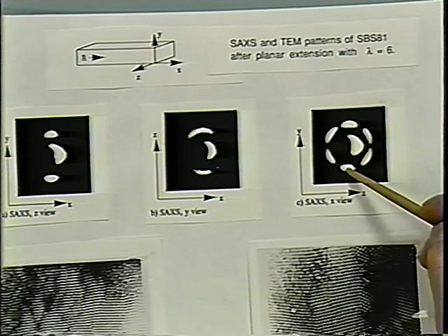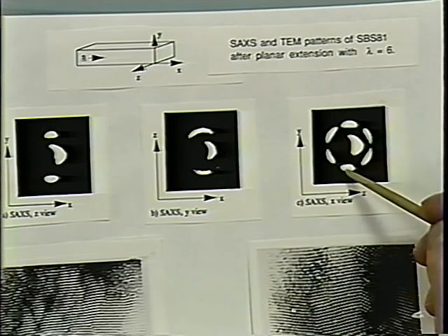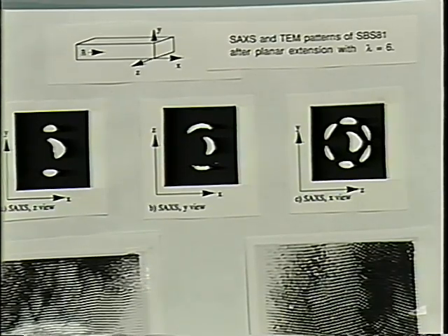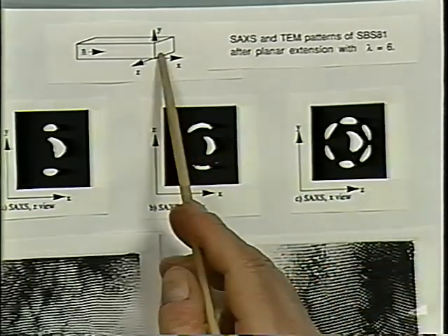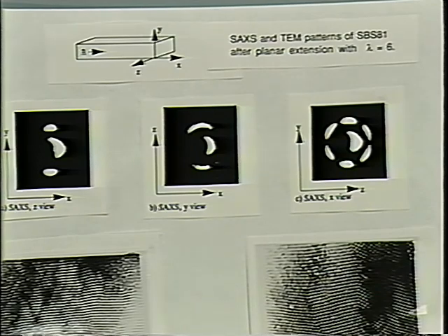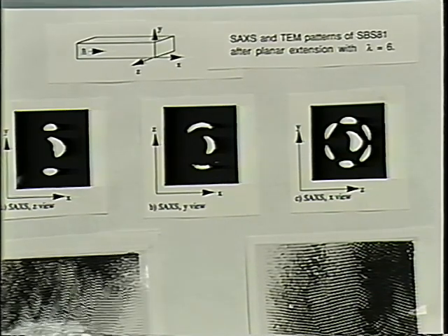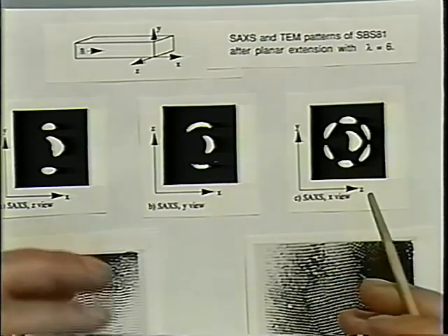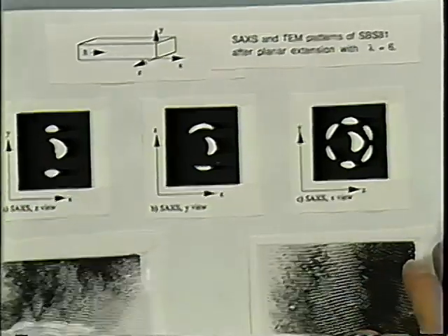And the thermodynamics is so strong that we cannot overcome that by flow. So the spacing is always maintained. The deformation here has been followed by annealing at 120 degrees for 2 hours. We try to introduce some order by flow and then heal any rupture which we produce by the deformation to get the most perfect structure.